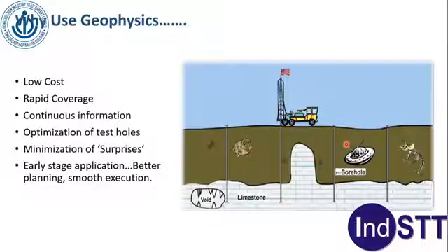Then comes the next objective, determining rock hardness, rock quality and bedrock depth. It is desirable to have information on depth of bedrock, hardness of rock, quality of rock, that is fractured, jointed, etc. to choose the right tool for the trenchless operation. And a geophysical solution for that exists, that is seismic refraction.